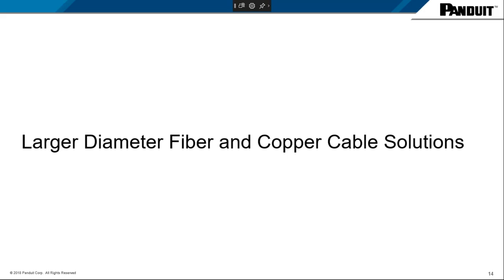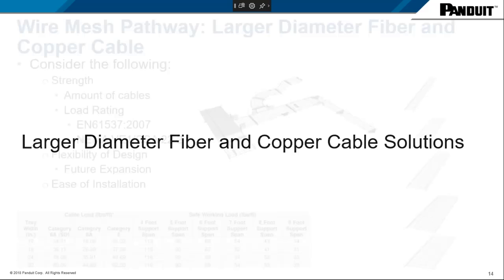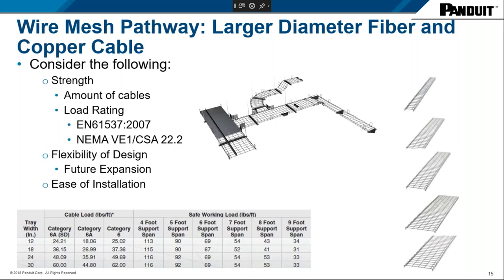So now I'm going to discuss, where do you hold large diameter fiber and copper cable? We discussed the importance of having a proper pathway for smaller fiber diameter cables. Now, what do we do with the rest of the cables? We recommend that for those larger diameter cables, for the copper cables, it is perfectly reasonable to install them on a wire mesh pathway.